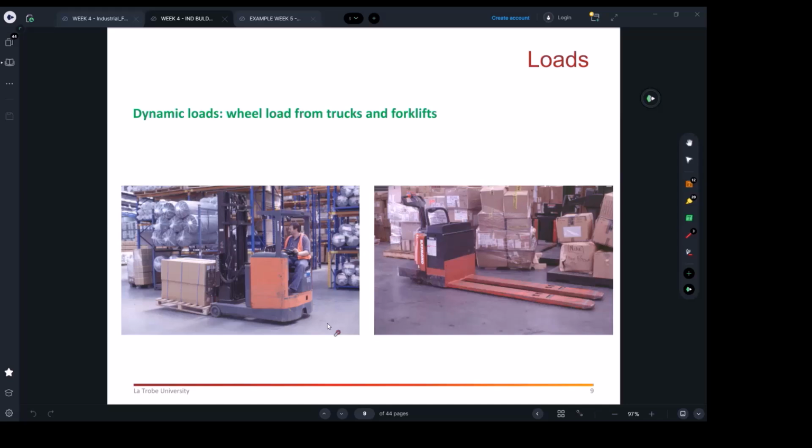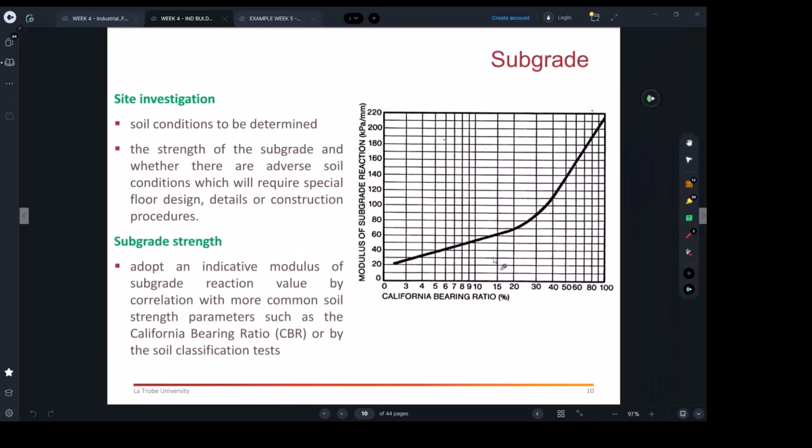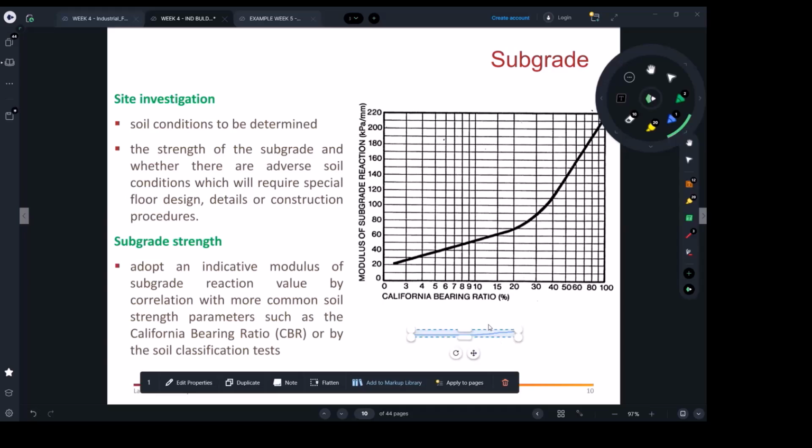And whenever you build something there, the soil report will tell you there is about 2 meters or so of fill. So definitely you're going to need piles, and that's additional cost. Which again, if you don't understand what the drawings are saying, you may miss that. And if you sign a contract to build something and you missed such an issue, that will be costing.